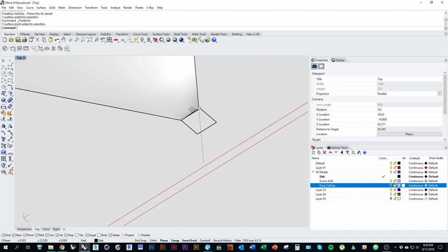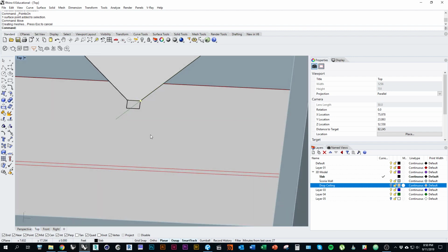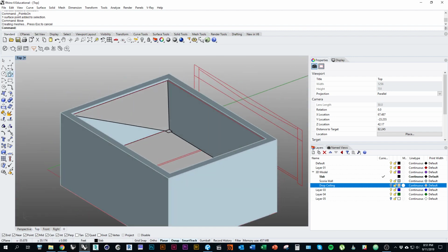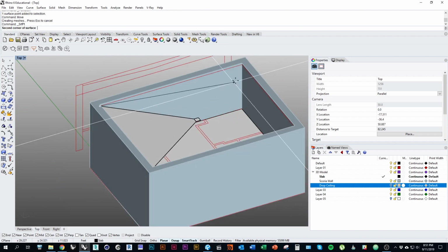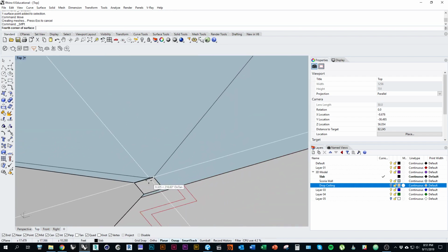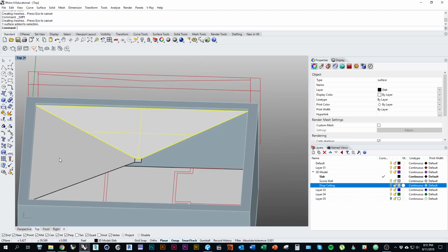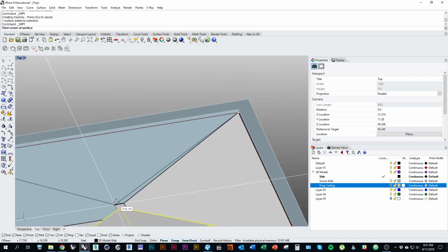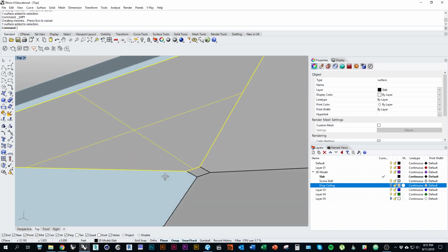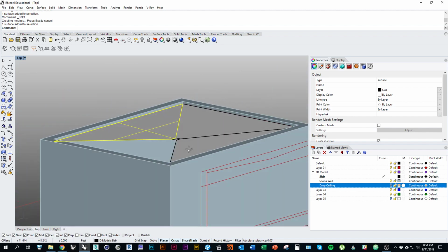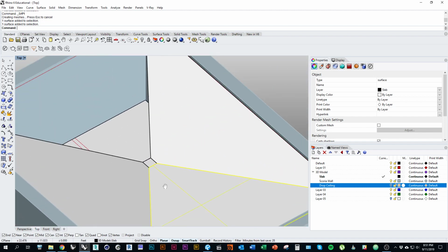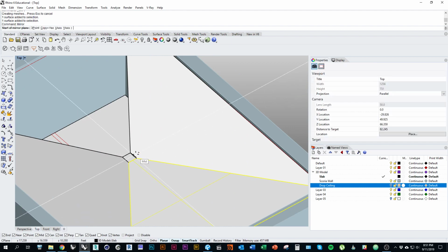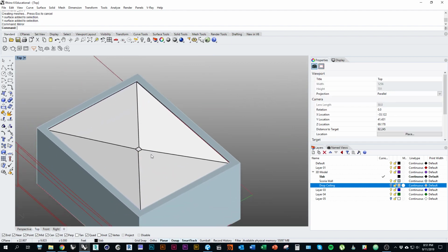Then I could select one of those control points, type in move, snap to that point, and then snap it to the end of the inside of the ceiling. So once again, I could do 1, 2, 3, 4. Again, you will have to draw them kind of in a circle, because if you go left, right, oh weird, maybe they fixed that. They used to make a twisted surface. Guess it doesn't anymore. But once you've drawn the 2 directions, you can just mirror them.